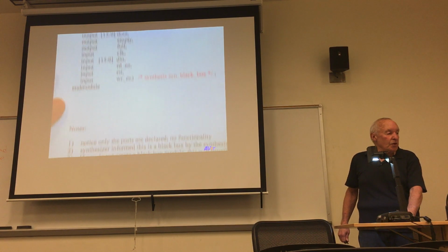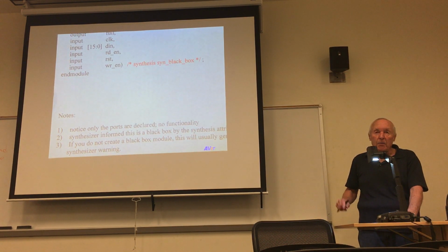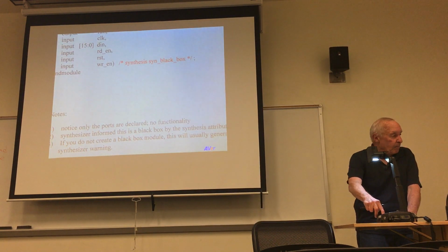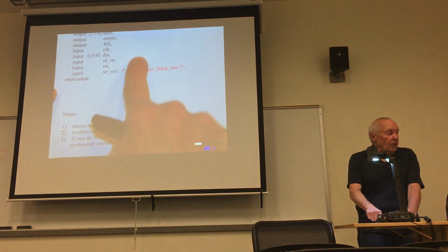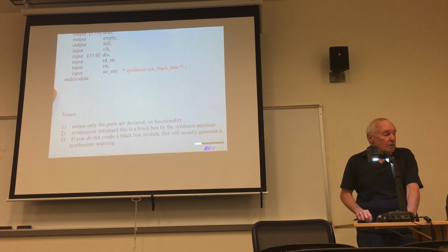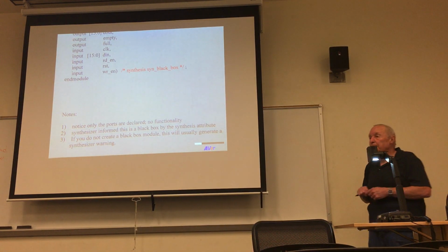Now there's some notes associated with this. Again, you're only defining the ports, no functionality. This synthesis attribute right here informs the synthesizer that this is a black box. If you do not create a black box module, this will generate a synthesizer warning.